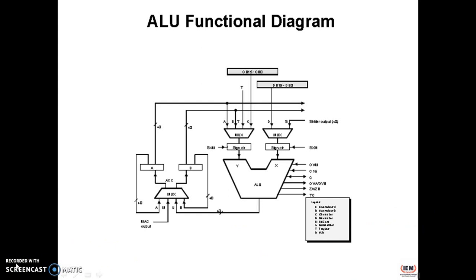Now also present on chip is dual access RAM, DARAM. The DARAM is comprised of several blocks like CPU, peripheral, host port interface like HPI, and on-chip single access RAM also is there, SARAM. The SARAM is comprised of again several blocks like CPU, peripheral and other parts. On-chip memory security also present with the C54 is a maskable memory security option to protect the content of on-chip memory present on this processor.